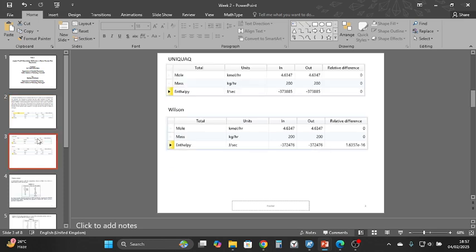I just want to discuss that top part. We usually do this with the help of regression. I am going to show it from my end also, but you also try to apply yourself and find out through regression which property method is the best. The best way to do it is to calculate the RMSE values between the experimental data and the regression that you will perform in Aspen. So try it on your own.